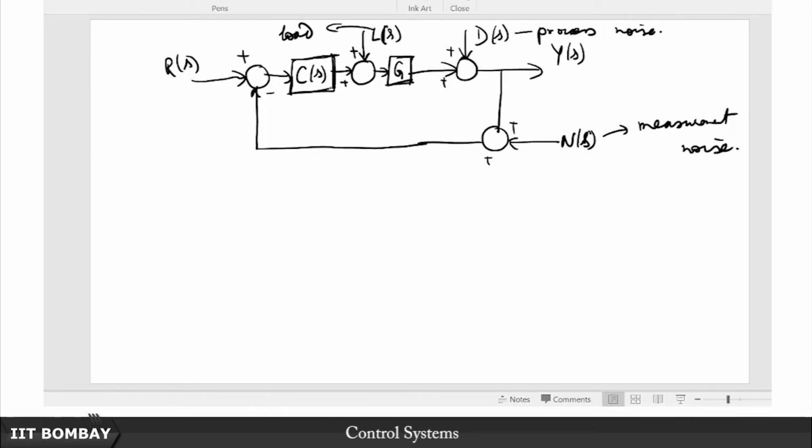Remember where this D and S and NS are coming from? Because of inadequate modeling, okay. We cannot account for every single thing in a model, in a systems model. So we have to make leeway for that. So that is why we accommodate these process noises and measurement noises and say that, okay, fine, this is where we draw the line between accuracy in modeling, and now we let these process noises and measurement noises account for the inaccuracies or the uncertainties in the system.